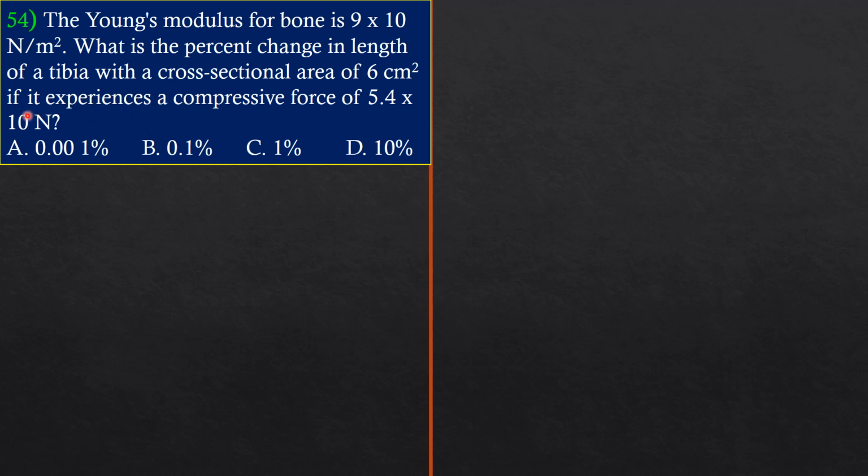Okay, so friends, in such a case, let's simply recall that the Young's modulus is simply given as the ratio of stress over strain. In this case, guys, we make the strain the subject. The strain is simply given as the stress over the Young's modulus E. The stress has been given, guys, so we can get the strain. The stress, as you all know, is simply the force over the area, then divided by the Young's modulus, which has been given.